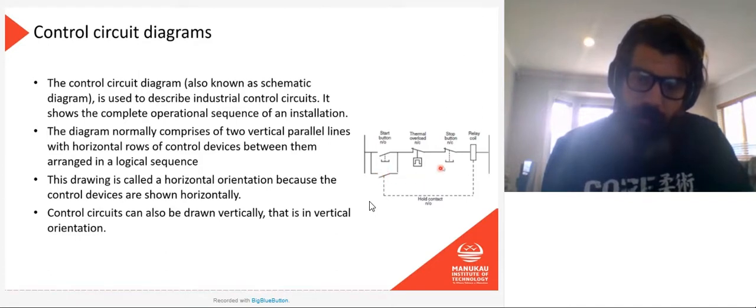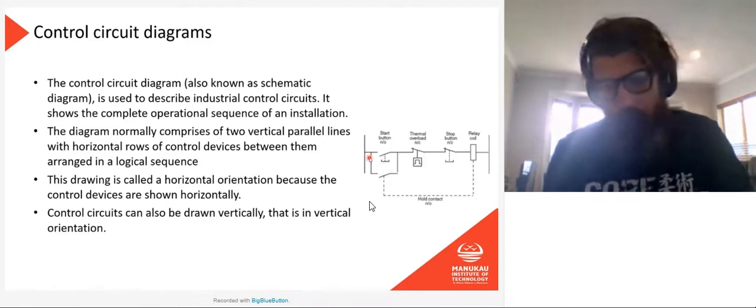That coil will just hold that contactor on. And then how do I stop it? Well, then I have the stop button. Once I push that stop button, then the relay coil is de-energized. This contact here opens, and therefore no current flows. The stop button isn't being held down. The holding coil is open. Therefore, no power will flow.